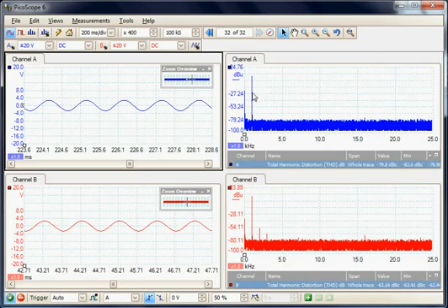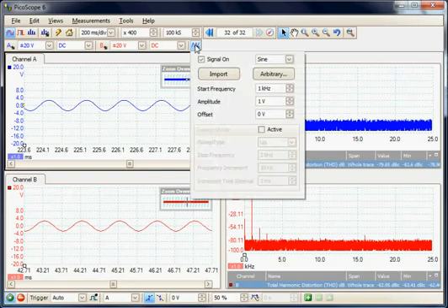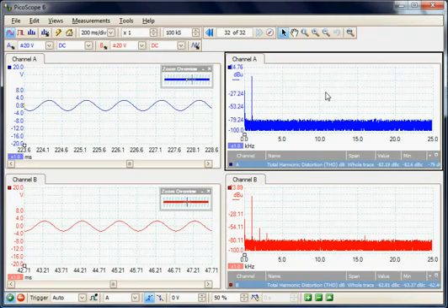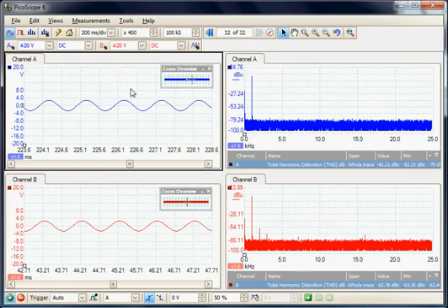So this is in fact a 1 kilohertz signal which is being generated in the internal generator. In fact it's generating a sine wave at 1 kilohertz. Other waveforms are available. And then the signal is being applied to the auxiliary input of channel A and B of the amplifier. The output is being developed across a 15 ohm load and then acquired with a ×10 probe.